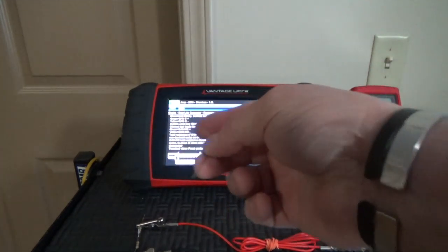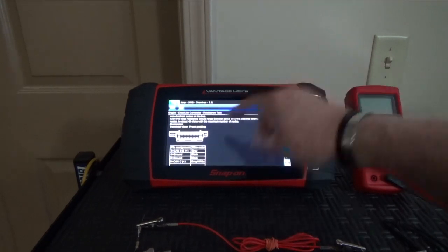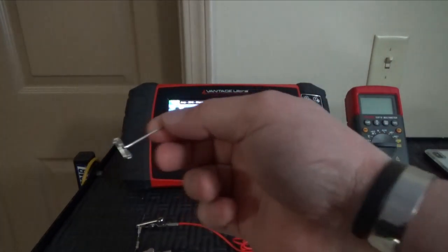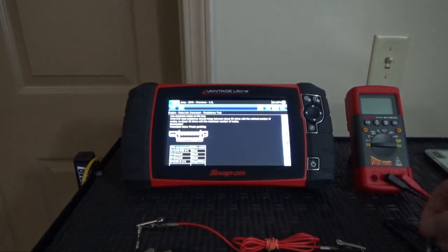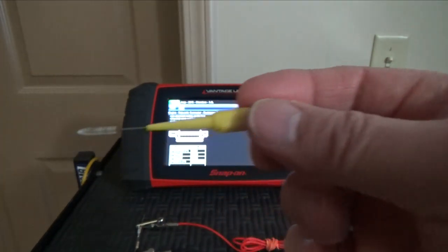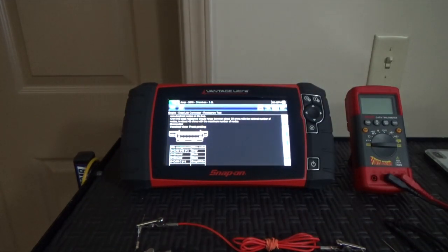You can back probe the OBD2 connector, not from the front, from behind, and you can use a T-pin. But when you are using the front, you want to use a very skinny probe like this that prevents the terminals from opening. So that's how you measure resistance in the CAN bus.